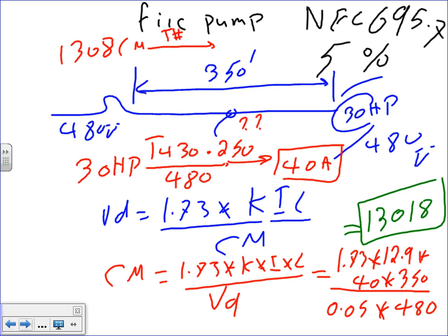Table number 8, chapter number 9 in the NEC. What do you get? I have 2 gentlemen agree on number 8. Now, Brad, you're going to go 13,018 or higher. This time higher because we're not looking at resistance. So you need to find yourself 13,018 or higher. So it's number 8? Yeah. Number 8. And don't be scared, guys, that number 8, that's small.